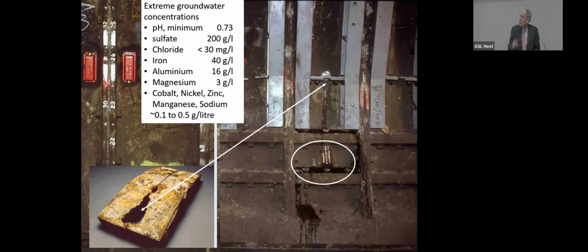And they put some strain gauges on the red boxes there, onto the webs of the cast iron segments, and the drilling and tapping of those led to a little bit of crack initiation. Then one ring cracked, and then the next, and then the next, and then they strapped it up. But the acid, pH of 0.7, pretty low. That was extreme. Sulfate at 200 grams a liter.